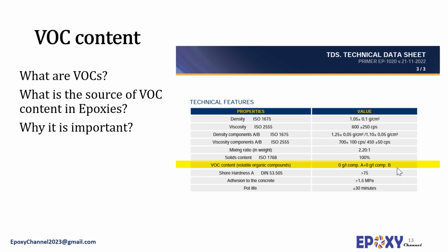This refers to the volatile organic compounds that make it up. VOCs are what give epoxy its odor. Concerning epoxies, the VOC source can be the solvent that has been used to modify the viscosity of the resin. Therefore, 100% solid epoxy contains no volatile organic compounds or VOCs.